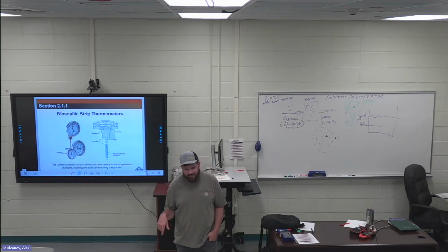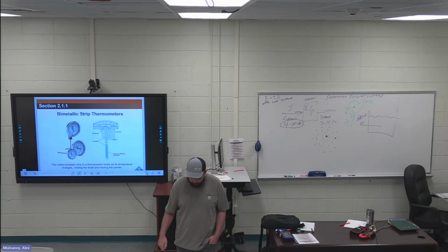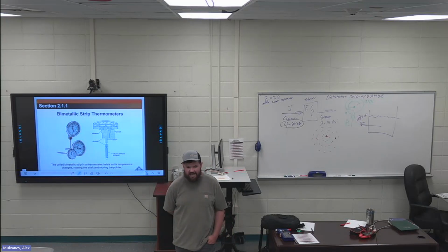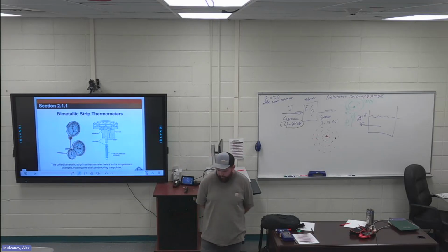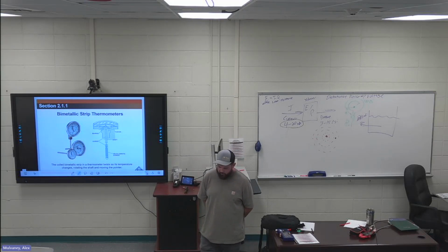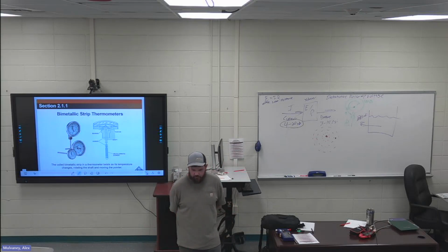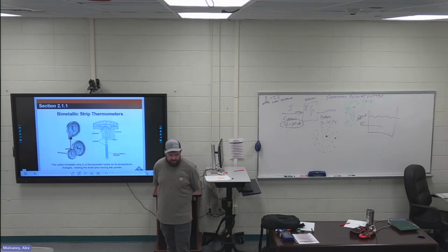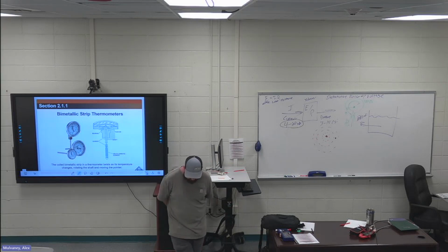Going along with this highlight is the sentence in the top right of the page. For thermocouples and thermocouple extension wires, the color red designates the negative wire. That's for all thermocouples. You need to remember that. Those two highlights go together. If you want to put an arrow between them, ISA created the standard. Red is negative.